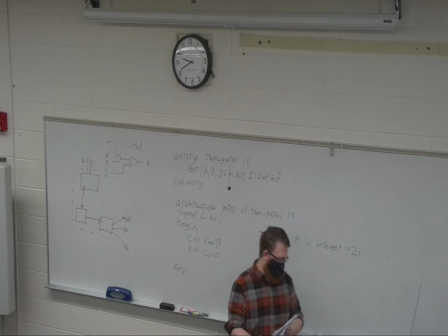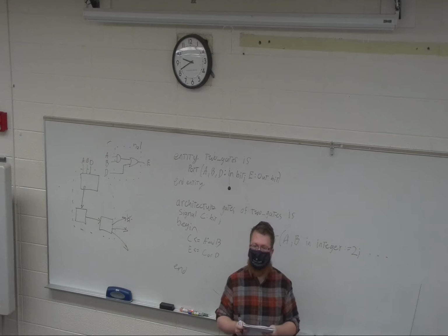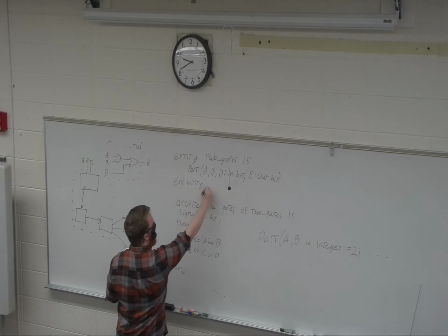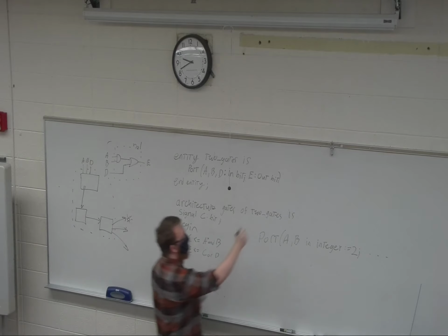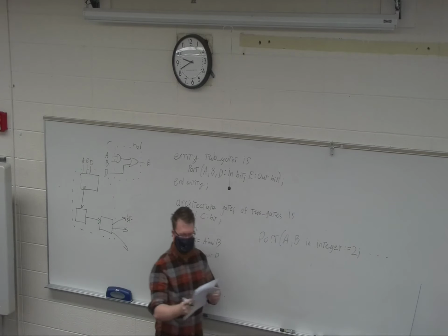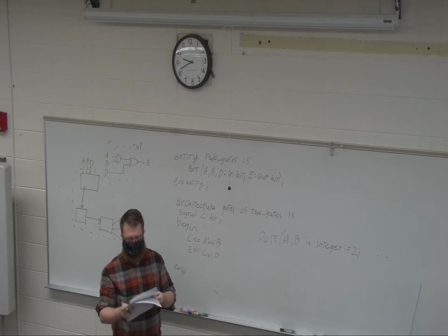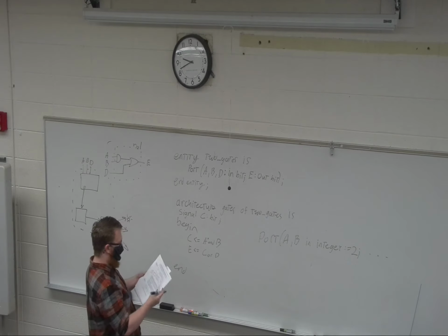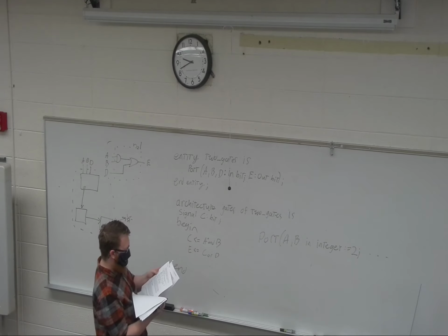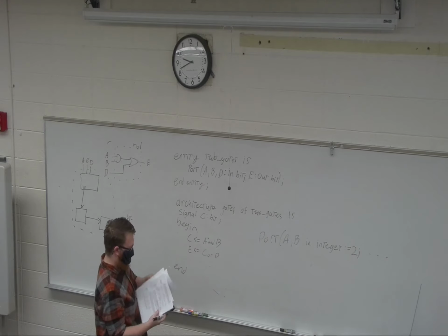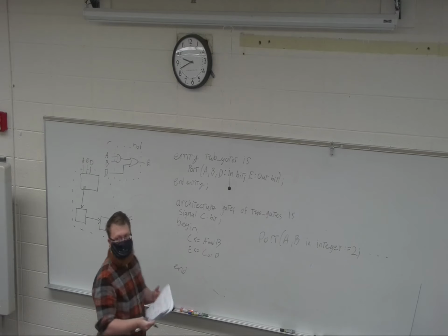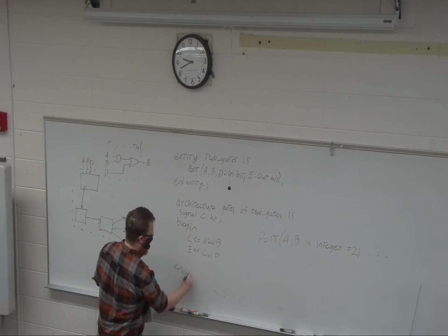But here's the architecture. So, do you need semicolons after the word map thing, or after the entity? After the entity, no. After end entity, yes. After port, I believe yes. Let me double check that one. Yes. What about begin and end? You need it at end. I don't think you need it on begin. I do need it at the end for sure. I just don't think I need it on begin. So, not begin, yes, end.